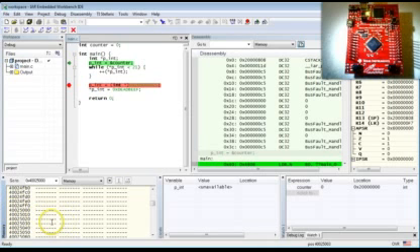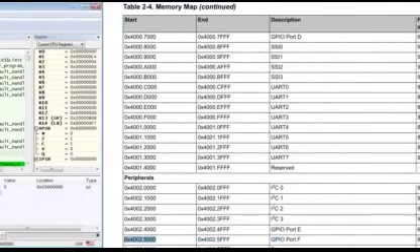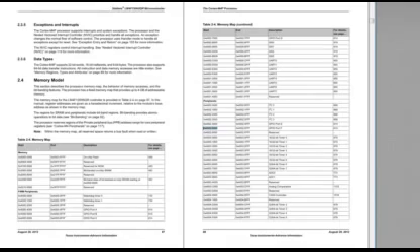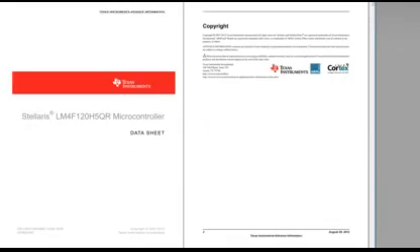The technique of blocking the clock signal to certain parts of the chip, called clock gating, is a very common practice in modern microcontrollers. So first you need to discover how to turn the GPIO F block on, which means you need to go back to the datasheet. Go back to the beginning of the document and search for the string "clock gating".